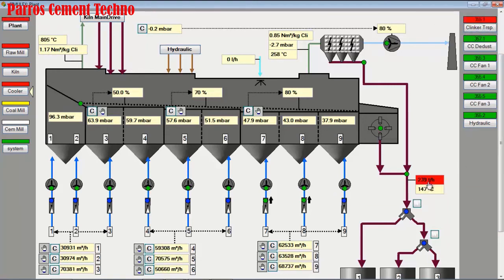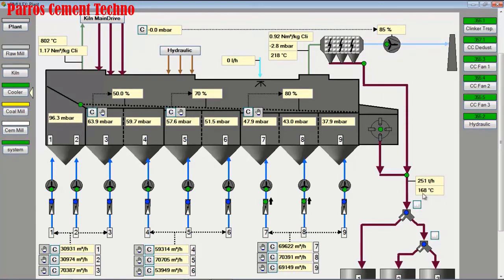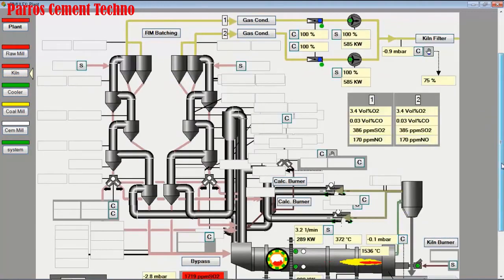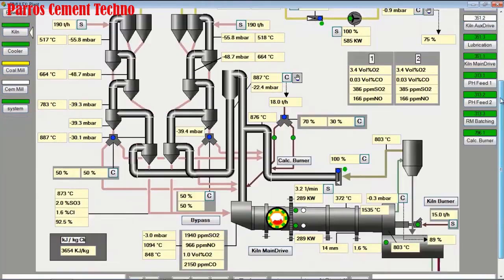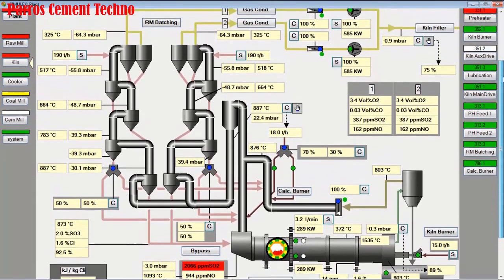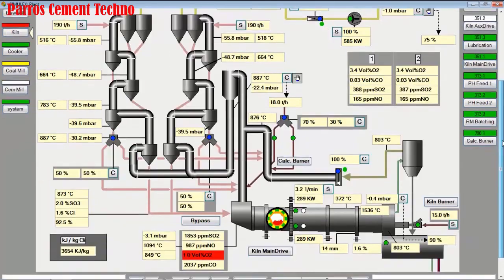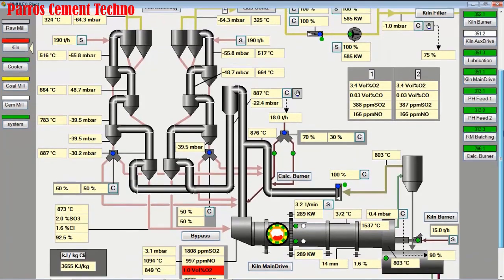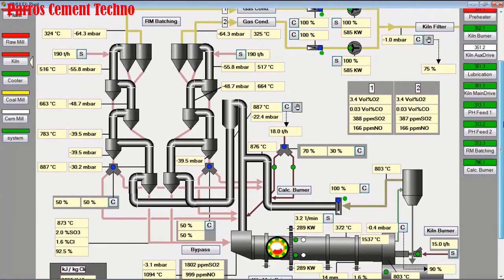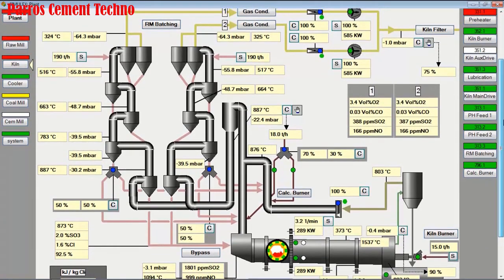Because the speed of grate 8 was increased earlier, the clinker on the apron conveyor has increased slightly, and now it is normal and the temperature is also normal. We look at the kiln operation control parameters, here we see the O2 at the kiln inlet is sometimes below 1%, and CO rises. Free lime is 1.6%, and kiln feed is 380 tons per hour, the highest preheater temperature is 324 degrees Celsius, because the ID fan preheater speed is already 100%.